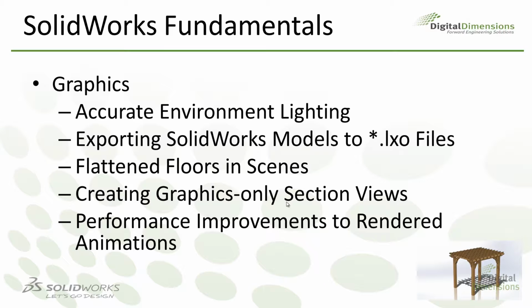So for those having issues with shadows caused by environment lighting in PhotoView 360 and previous versions, there's a new option in your scene for accurate environment lighting. Now it's going to slow the performance of the render down, but it'll give you more accurate shadows from your environment lighting in PhotoView. Also in 2014 is the support for exporting SOLIDWORKS models to LXO files, Luxology Scene. So if you work with Modo, it's a very common format, and now we can export SOLIDWORKS models to that format, LXO.